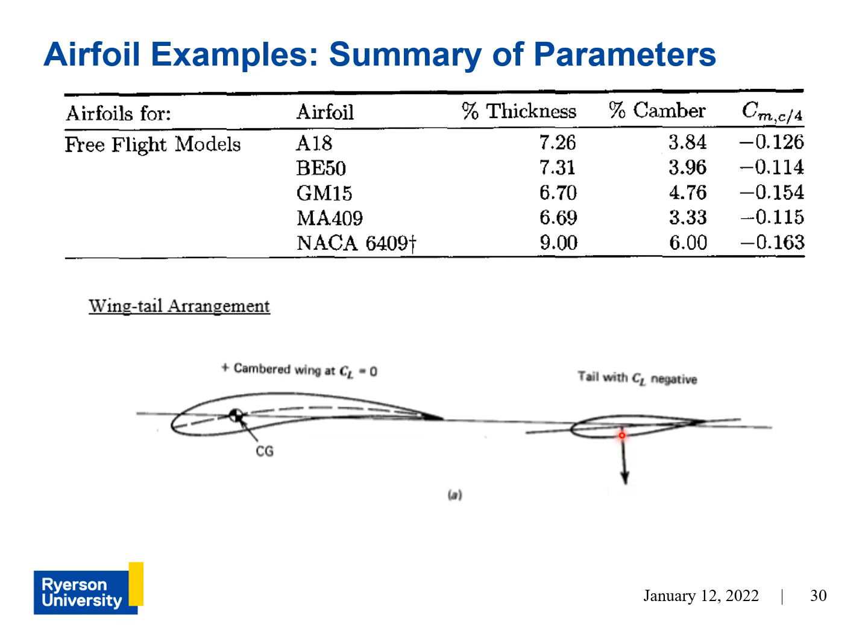So the lift force will actually be downwards, and that will counter the negative pitching moment caused by the wing itself. So that's the main purpose of the tail right here. And again, canceling out the moment caused by the wing body is called trim.